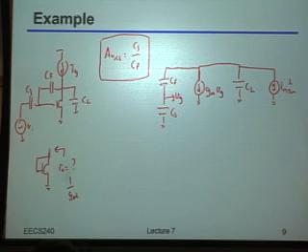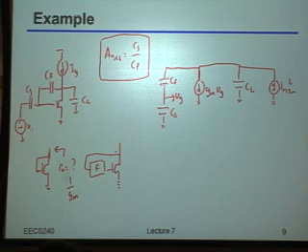Now let me ask you a slightly more complicated question, although still I claim very easy. Now what I want to do is take the same transistor, and I'm still going to tie it in a quote-unquote diode configuration, but instead of directly connecting the drain to the gate, I'm going to connect it through this gain that I'm going to call F, where, by the way, F is going to be less than 1. So now, what's the output impedance? One over F GM. Okay, there we go.